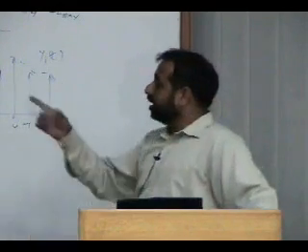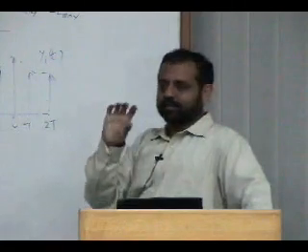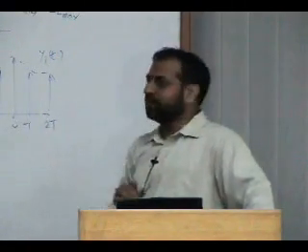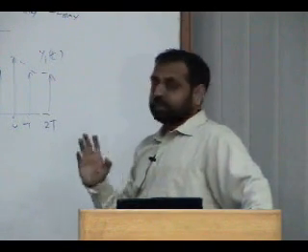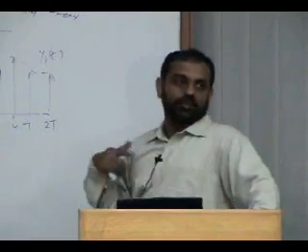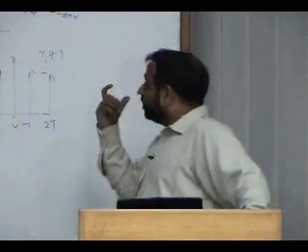Okay, so there we went from time domain to frequency domain to understand the sampling theorem, also called Nyquist sampling criteria, which says that you got to sample at twice the maximum frequency. Here, in order to understand the reconstruction process, you need to go from frequency domain to time domain. So what do you get in time domain?